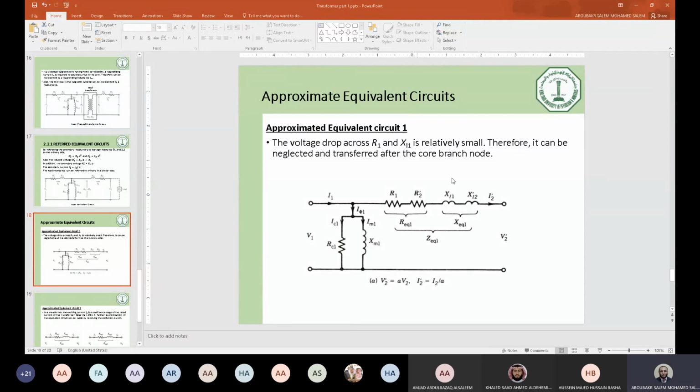So this is now the equivalent impedance of the two windings. And here is I1, and this is I2 moving in all of the windings. So in this case, you can make only one loop because the voltage here will be V1, and simply you can calculate I2 prime as V1 divided by the impedance of the winding plus the load impedance.